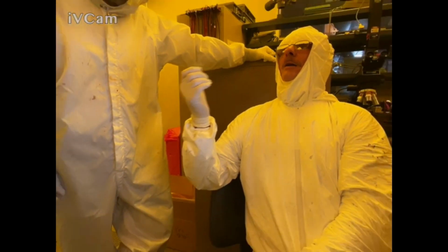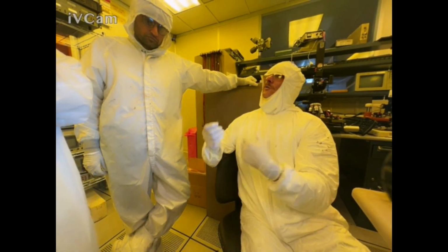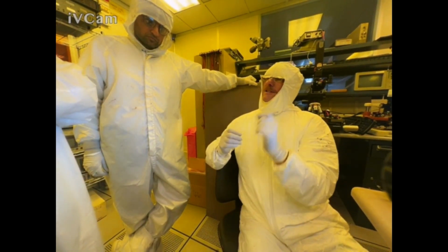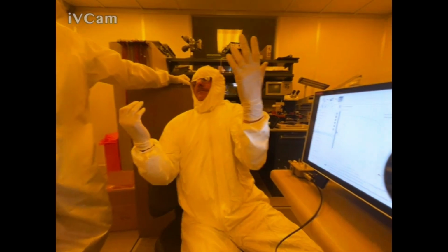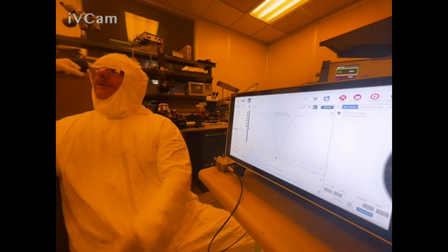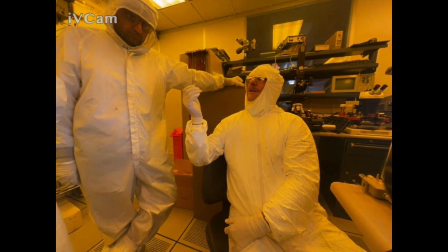Because what you care about is gate capacitance, right? Because you want a device that can switch fast, so you want low capacitance. But there's parasitic capacitances between every 2 pins on a device. It's physics, right? So by shorting out those 3 pins, I've eliminated those capacitors. They're gone.